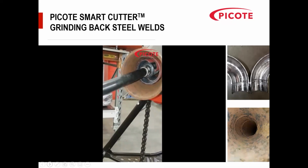So you can grind lots of materials away. We can take out liners with this. We can cut through lateral reinstatements, etc., tree roots, and descaling pipes.